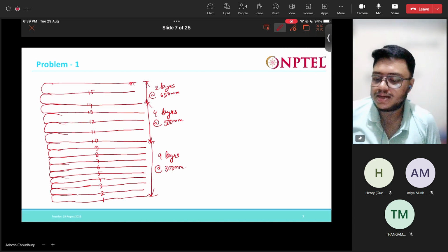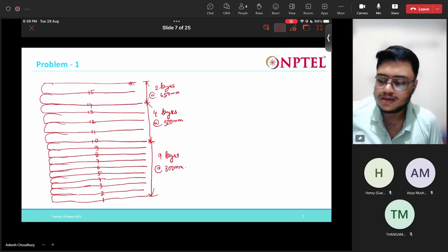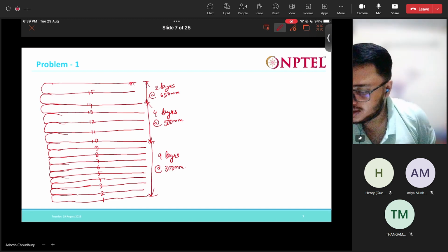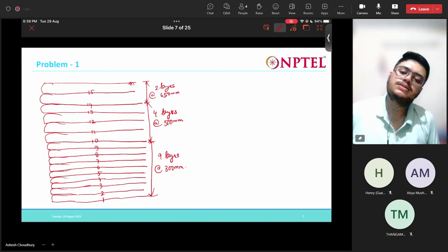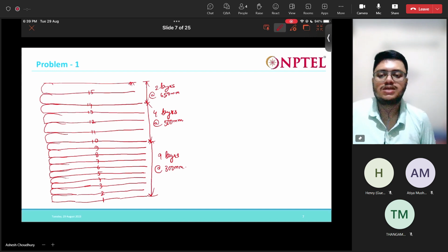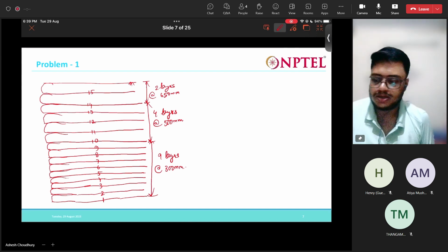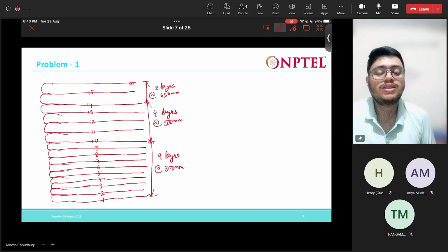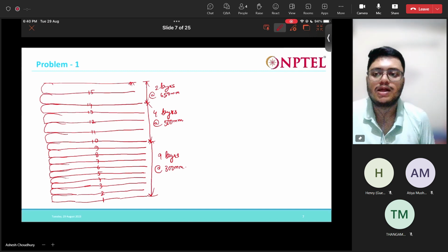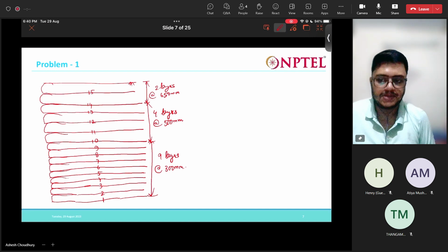It satisfies the internal stability requirement, that is the tensile pull out, this rupture and the pull out rate. Till now, what we have done is that we have just satisfied this rupture criteria. Okay, utilize the rupture criteria to determine the spacing.